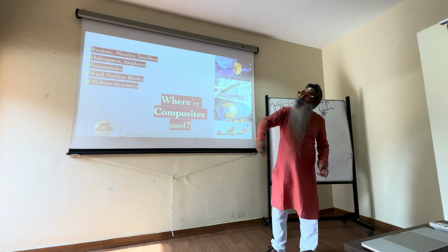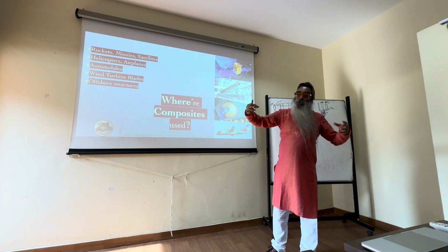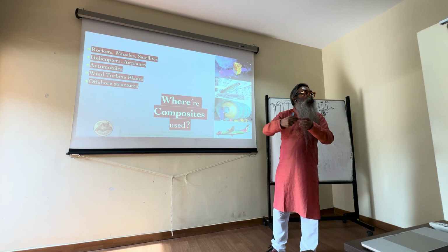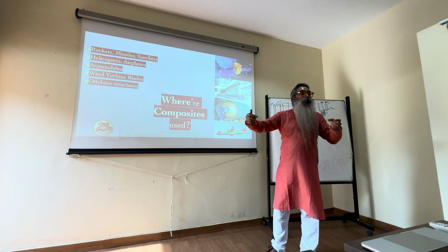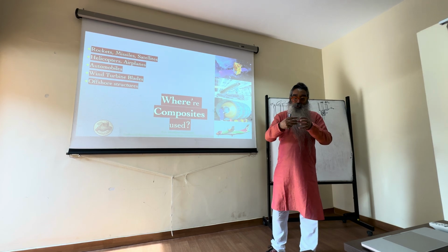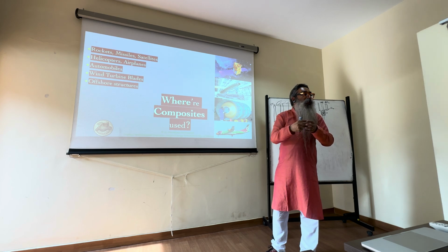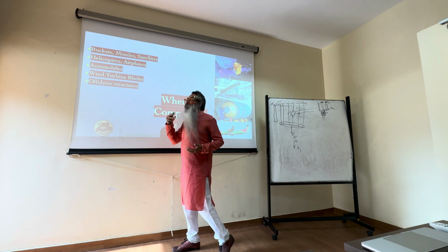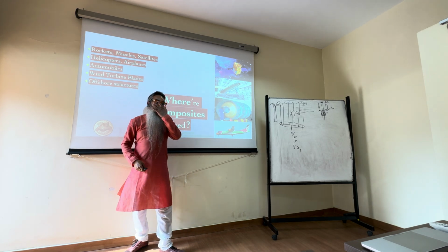But then when you're trying to join two composite pipes, because you can't have hundreds of kilometers of a single pipe, right? So you have to bring two pipes every now and then to join them, and these pipes can undergo, because of the changes in temperature of the water, expansion and contraction. Which means the joint should be capable of that. So many of these composite joints are actually manufactured out of that, and that's some of the designs that we did while I was at Georgia Tech.